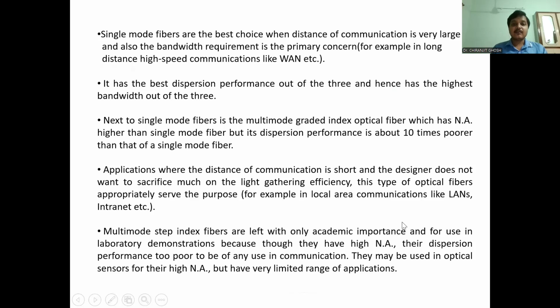So a question asked, which type of fiber is suitable for long haul communication? So always we have to note the single mode step index fiber is used for long haul communication. Okay, because it has less dispersion, no dispersion actually, very minimal dispersion, and also it has very less attenuation.